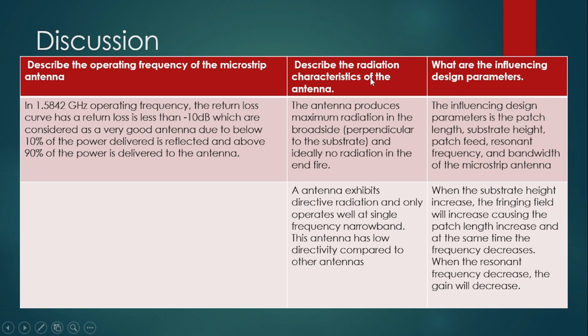For the radiation characteristic, the antenna produces maximum radiation in the broadside, perpendicular to the substrate, and ideally no radiation in the end-fire. The antenna has highly directive radiation and only operates well at a single frequency, narrowband. This antenna has low directivity compared to other antennas.